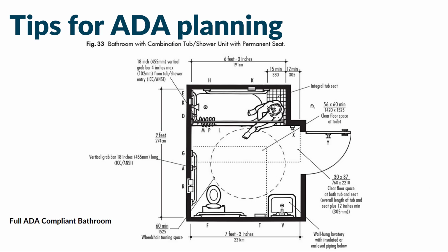Okay, and then here is a fully ADA compliant full bathroom that probably has all of the measurements and things you might need to know, or nearly so, in a really highly functional space. And I think probably, if you get your 60-inch minimum wheelchair turning radius in the center, you're going to be in pretty good shape, because then you'll see after this, you're getting your clearance on the side of your shower bathtub with the integrated built-in seat.